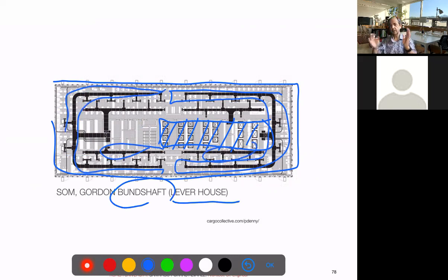So it's kind of symmetrical. As you know, that reduces the size of the shafts, and you can see how big the main ducts are. And you have a very nicely distributed system, which is fitting mostly the working spaces. And you have less concentration where you have all these closed rooms and the archives and elements which do not need so much air.